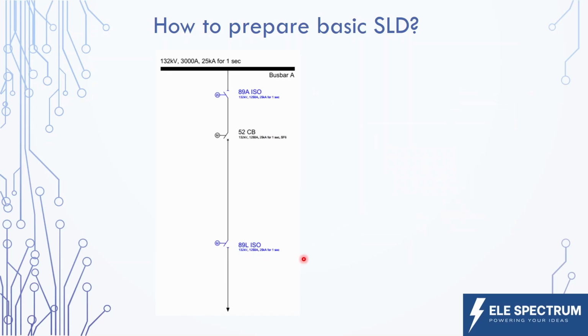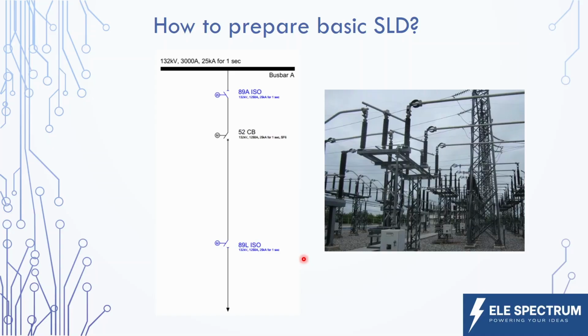Let's see another photo of disconnector. Here this is a different type of disconnector where we have double break type of disconnection. That means here, as you can see, we have these three insulators, and this is one part of the circuit, this is another part of the circuit, and at the center we have this moving part. So altogether both the connections are disconnected or connected.